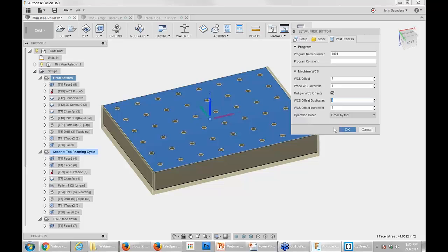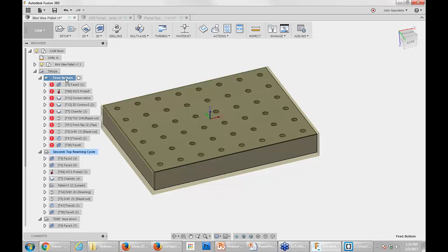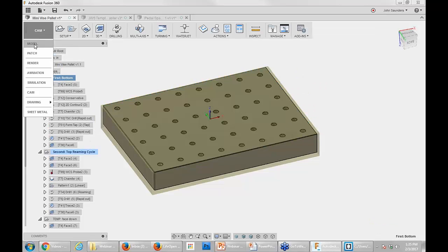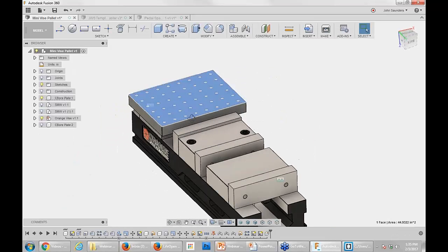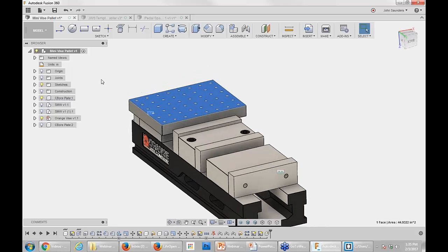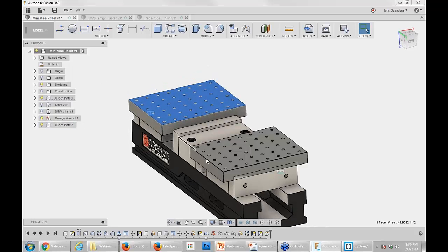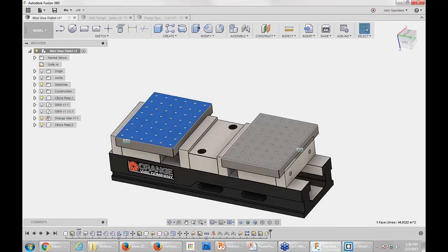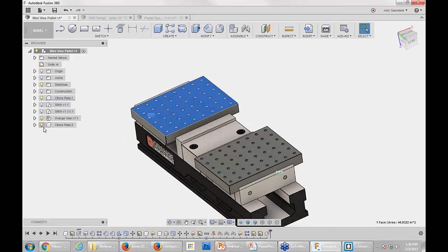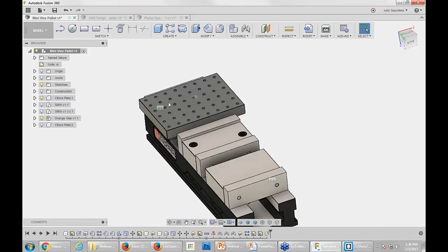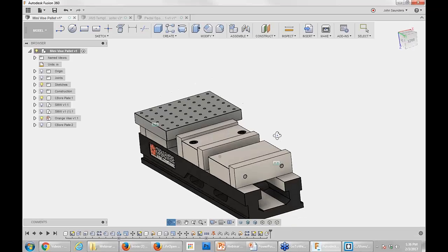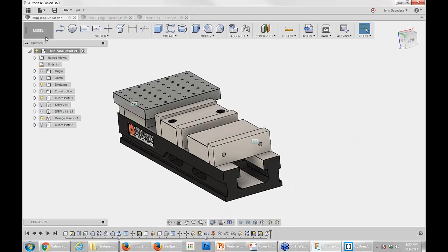So with this, what this does is it does a G54 and a G55. So if we go back to the model side, there's a part here, and then there's another version of that part. It happens to be right here in the front side of the vise, but you don't even need that to exist, because all that I do at my machine controller is I probe in. This one is G54, and then I find this one, and I set that as my G55, and you're done, which is super cool. And that's how, by the way, the probing works.